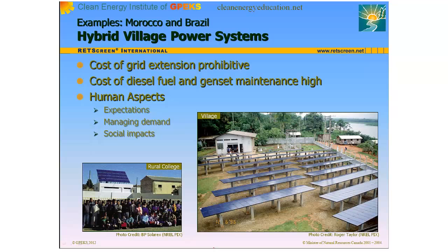The system must also include some mechanism to ration the electricity among the different system users, so that one user does not consume all, leaving the others with nothing. Such a mechanism should encourage use at times when the battery is full and the sunshine is strong, and discourage use when there is little energy available. Some people advocate imposing absolute limits on each subscriber's use of capacity and energy. Whatever the system, it should include safeguards to prevent theft of the electricity by unmetered loads.